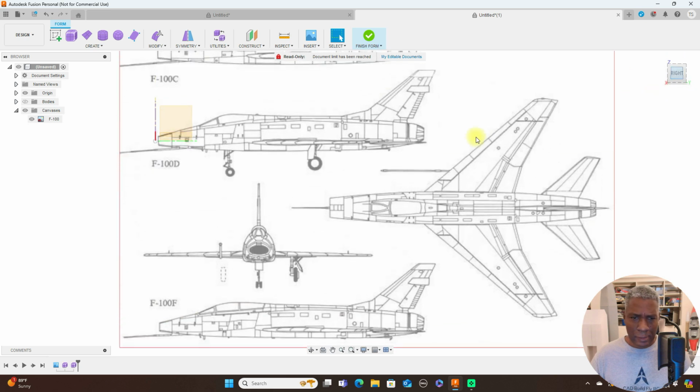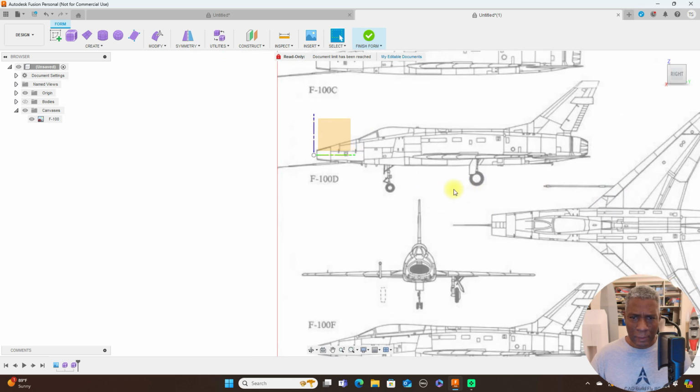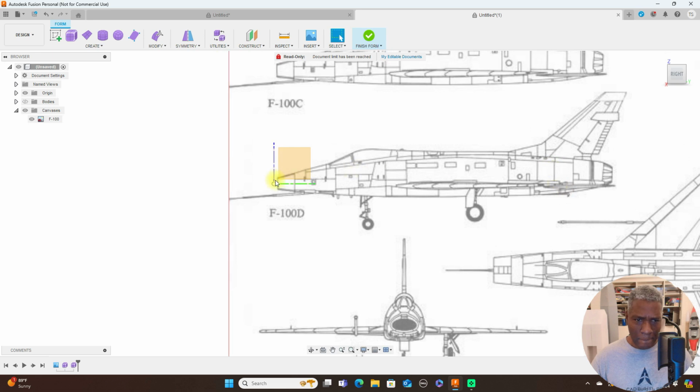Again, like this F100, this is two pieces here. Instead of, like on the A380, where I would have done that all as one. But this here, since I'm looking at this, will have to be done in two pieces. That's the only difference in workflow on this. So you would do an offset plane here, and then you would do a cylinder on this right here, and then stretch it back here to do the top of this, to get this.